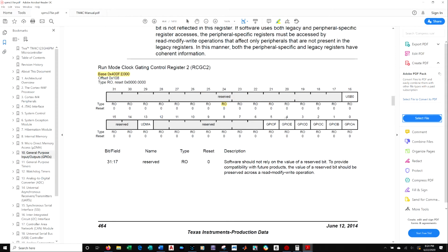This is the number I want to put right to that register, because I want a 1 in that 6th bit, which is bit 5. And once I put that in there, I see that in hexadecimal is 20. So when we write to this register, we're going to write hexadecimal 20 to get a 1 right here.